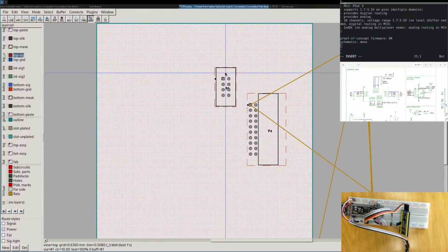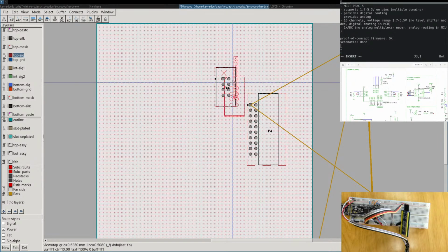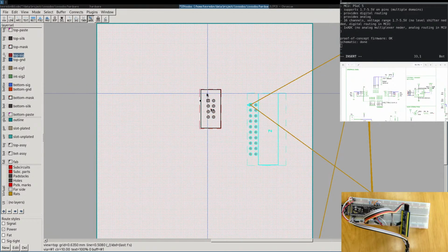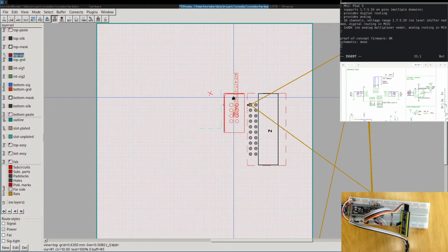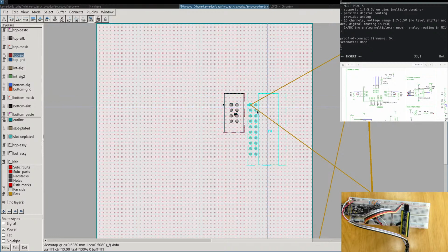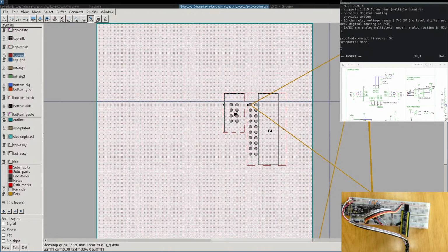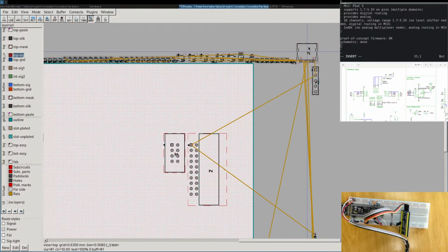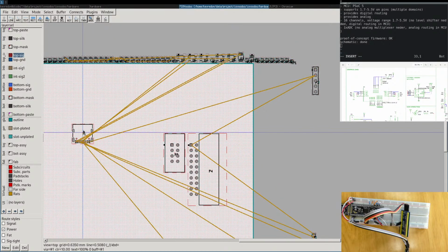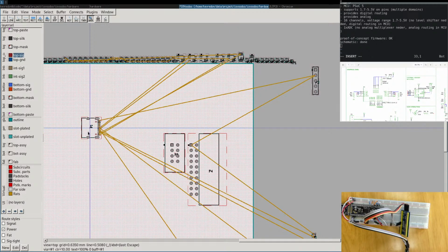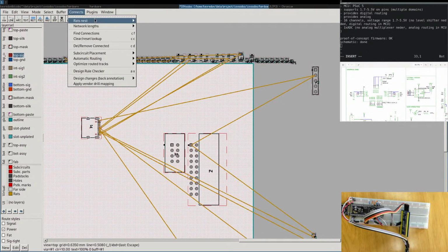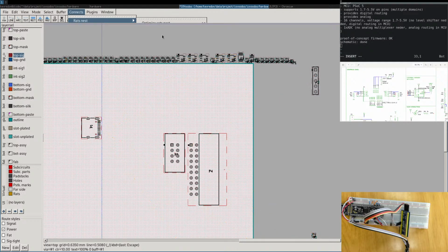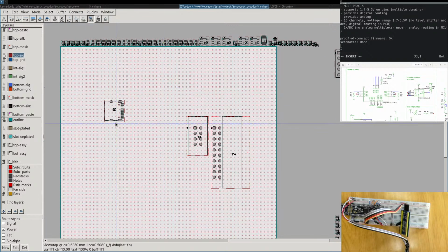And this will be the voltage selector. We want to have it very near this thing, because this is where, can we have the whole board as large as this connector? That would be nice. Up, rotate, it's F9. Yes, I still remember a couple of things. Then I want to get the rat's nest. Yes, rat's nest. Size, selected, erase. Don't want to watch them for now.